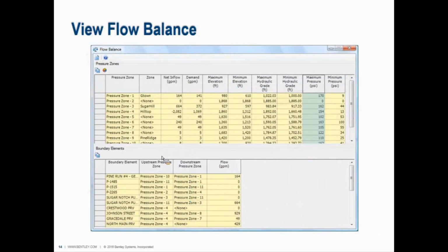You can look at the flow and the pressure into each pressure zone, minimum pressures, things like that. Some uses would be to determine if anyone in the pressure zone will have excessively low or high pressure, because you'll see over here on the right-hand side maximum pressure and minimum pressure. It's a very quick way to see what that range is on each of your pressure zones, because remember earlier I was saying there's kind of like a sweet spot range that works well, but then outside of that range it's tough to manage, or it's high variability for users, or it's a whole lot of equipment.